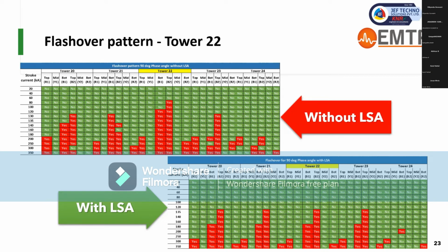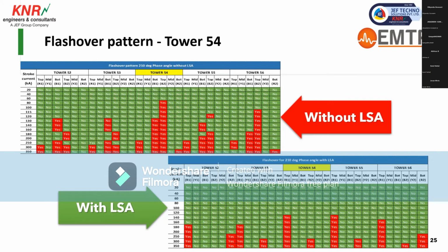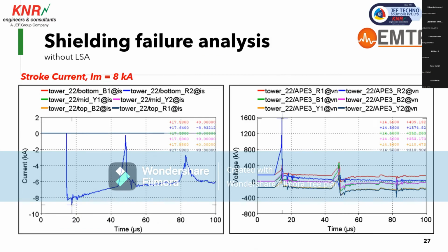In this way, we verify the spots where we install arresters. This process is done for each span where we install arresters, or for a representative section in case we have a large number of arrester installations. So this is the flashover waveform before and after installation of arresters.